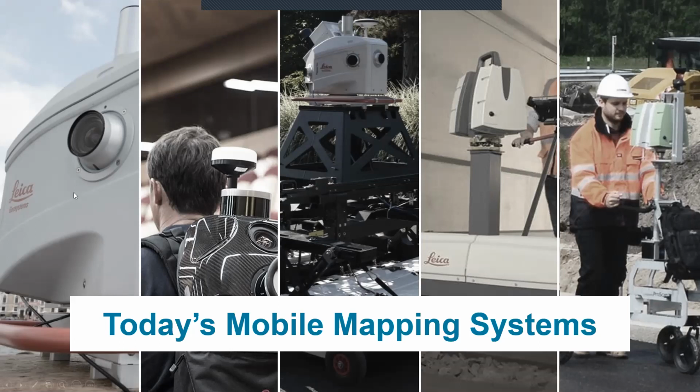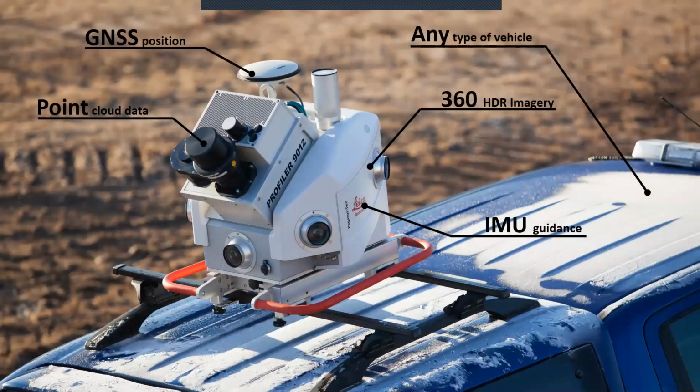Those can be mounted on a backpack, so a person can carry it on his back and move around the city. There are mobile mapping solutions that can be mounted for suburban and rural environments with GPR solutions, or we can have vehicle-mounted solutions and human-pushed trolley systems where we just push the scanners and collect the data. So these devices, mobile mappers, have enabled us to capture more areas.